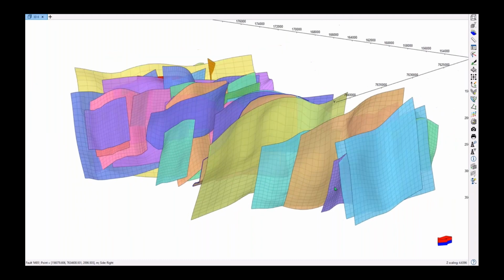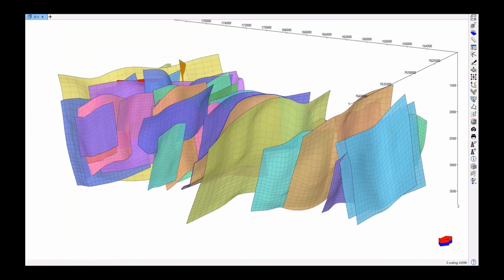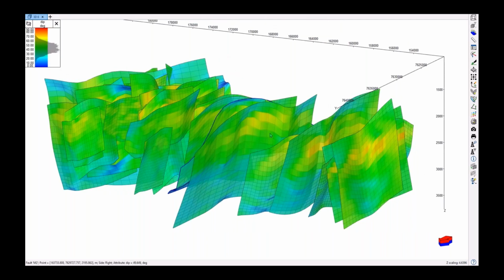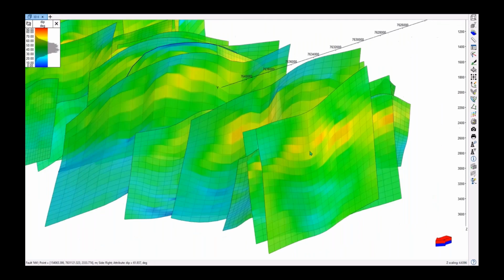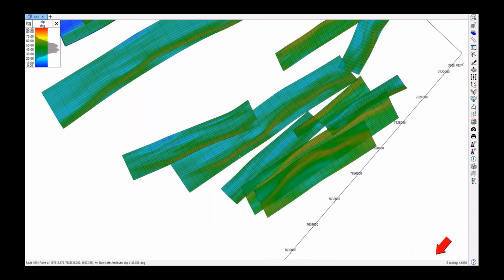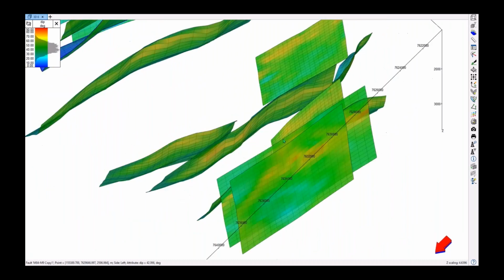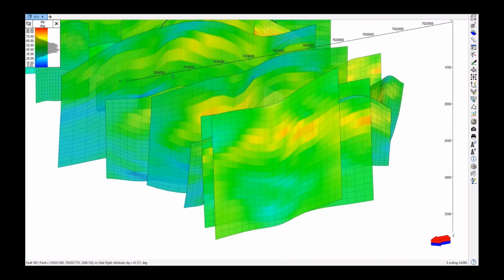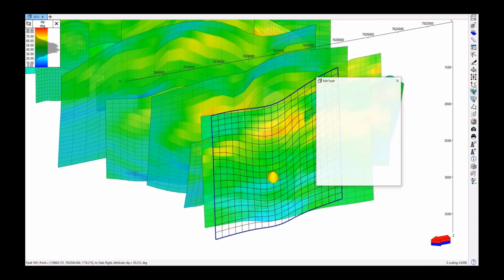So once I've created all my faults on seismic, I've popped it through to my 3D window here, and we're just visualizing them all. Before we create a nice 3D model, we want to make sure that our faults are error-free. We want all our sticks to be as planar as possible. These definitely will grid in the software, but if we want to have a little QC and check the dip of our faults or the angle of our faults, we can do this here.